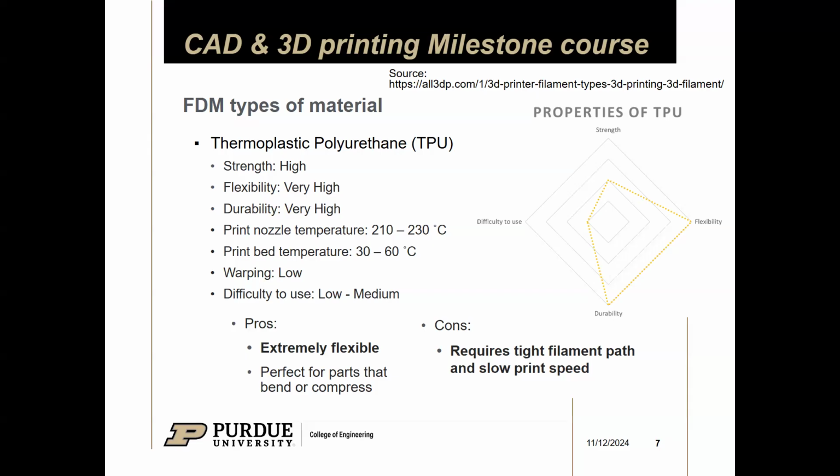The only downside is that you have to print a considerable amount slower compared to other materials just because it's so flexible. If you're not set up to print TPU, the filament can get jammed and shoot out the side of your extruder if you're not careful. That's less of a problem now, but it's pretty cool.